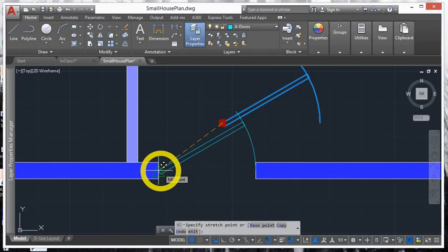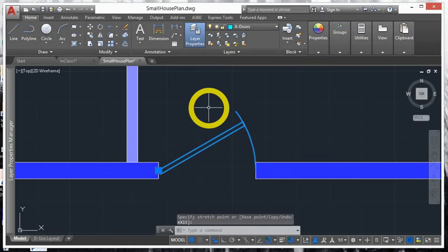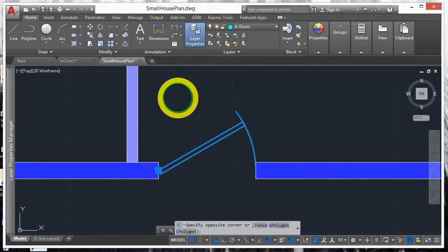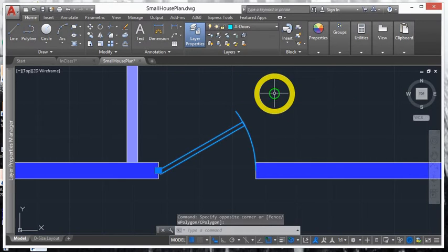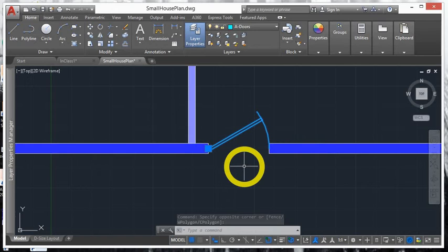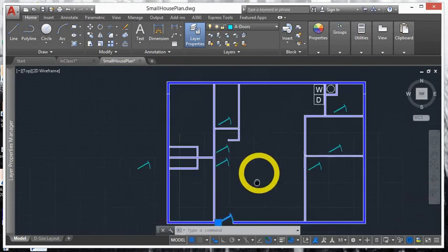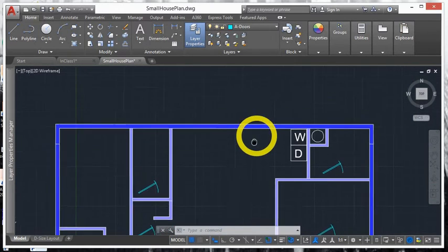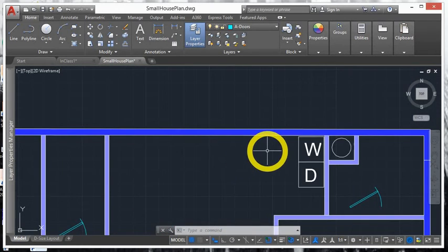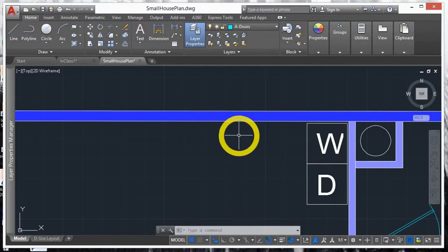You notice I'm catching the midpoint snap there. I can let go, and he's perfectly placed. Okay. So that's how we're going to place doors. Now, I had an opening already in the wall there, so how do I go ahead and make those openings? Well, we know we need an opening for another exterior door here for the back door for this house.